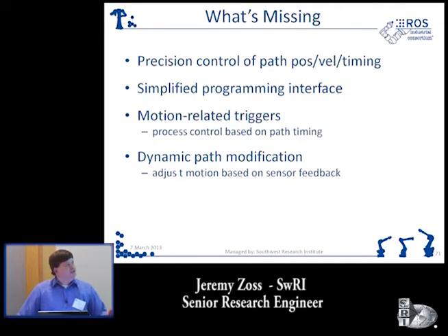Some of those tools are within ROS, but it's more geared towards currently flexible path generation to deal with dynamic environments. And if your process needs a very specific path that follows very specific motion constraints, then there may be a little work to do with ROS to guarantee that what comes out of the end of the robot is really what you need for your process.